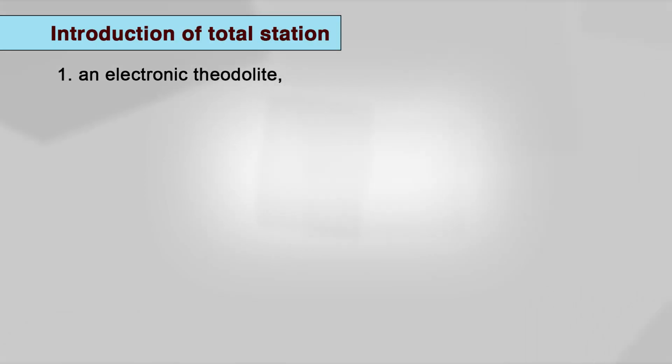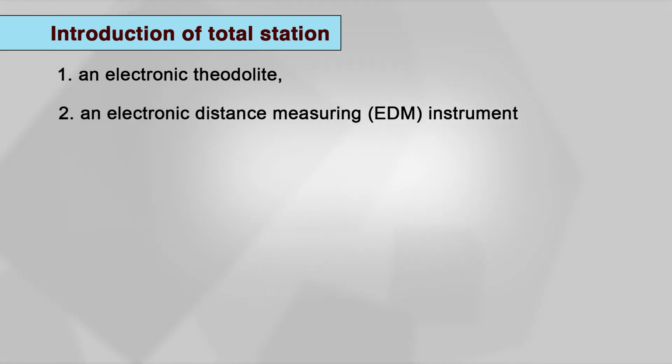Another part of the electronic theodolite is the tribrach. The tribrach forms the base of the instrument for fixing the upper part, that is the LED of the total station, with the tripod stand, primarily for leveling and centering of the total station. It is also used for making use of different instruments at the same setup, using the same leveling and centering arrangement.